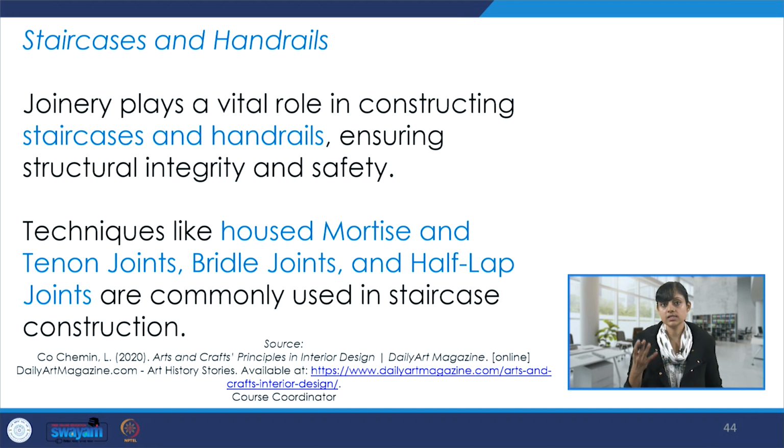Also, staircases and handrails, there also joinery plays a vital role. So, it plays a vital role in constructing staircases and handrails, ensuring structural integrity and safety. Safety is paramount. Techniques like housed mortise and tenon joints, bridle joints, half lap joints are commonly used in staircase construction.